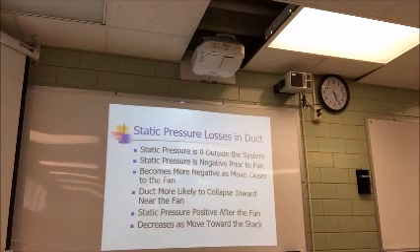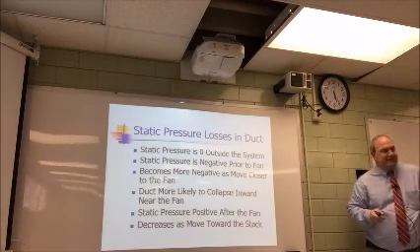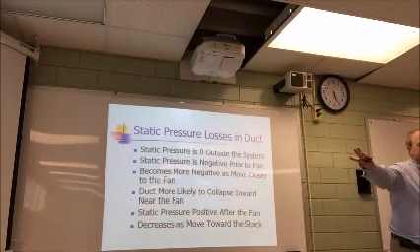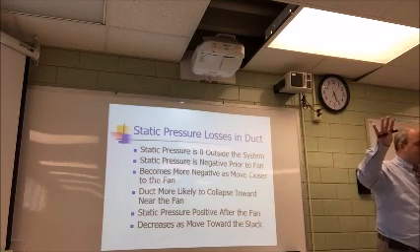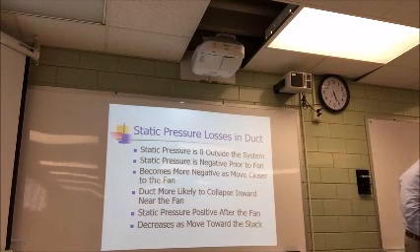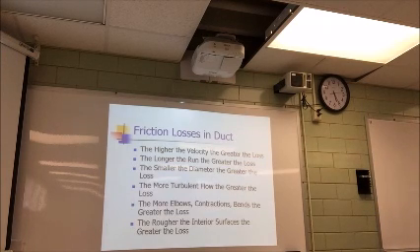Ducts are more likely to collapse inward near the fan, and static pressure is positive after the fan. And it will decrease. You guys think about it, if you have a fan pushing things through ventilation up to a stack, what's going to happen? It's going to slow down as it gets near the stack. Clear as mud, right? You guys just love ventilation.